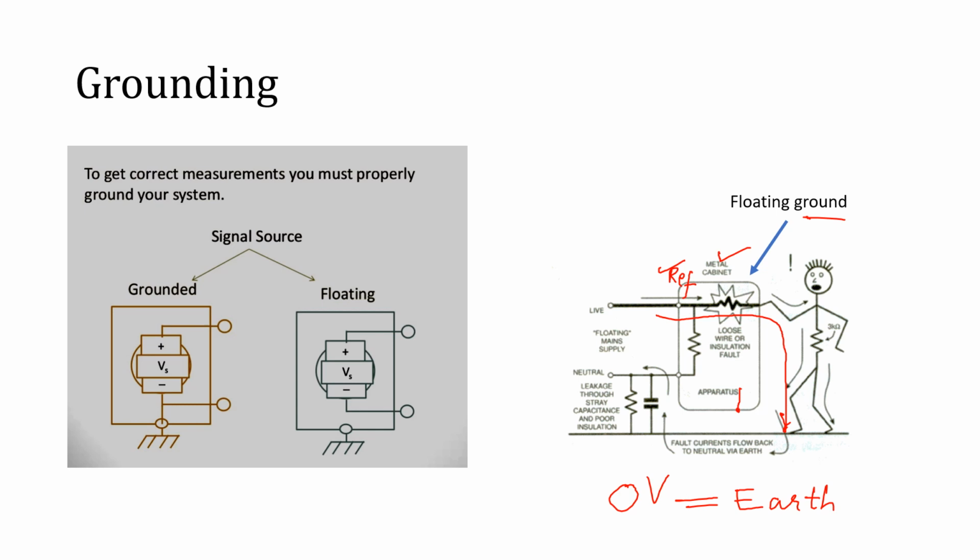So in this diagram it is explained what the best way is. When we have the device and its own circuit, that is, the current return is there, very good, negative and positive are connected properly, the circuit will work. But when you forget to connect this reference to the absolute reference, there may be many chances of floating ground and of a human getting an electric shock, and there are other disadvantages like current surge, high voltage and other noises. So it is always better to properly ground your interfacing circuit with the absolute ground.